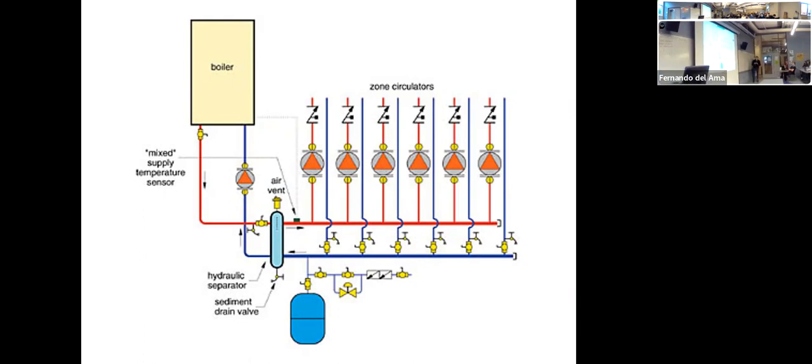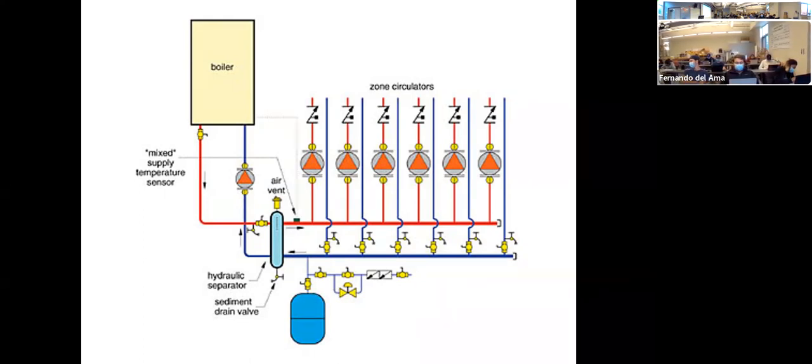But before every element or a radiator or whatever, we always need a valve. So if there's something here, I can cut off these valves and replace that element. And if there's another radiator here, I will have another valve, so that I can replace those elements without affecting the rest of the circuits.